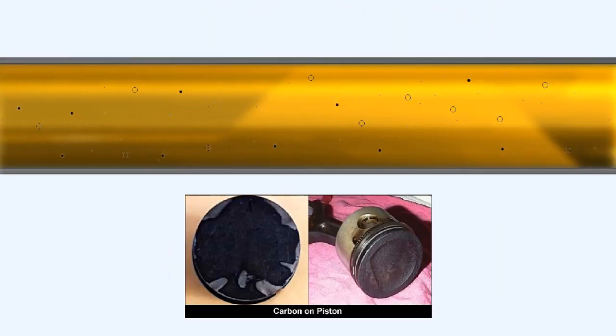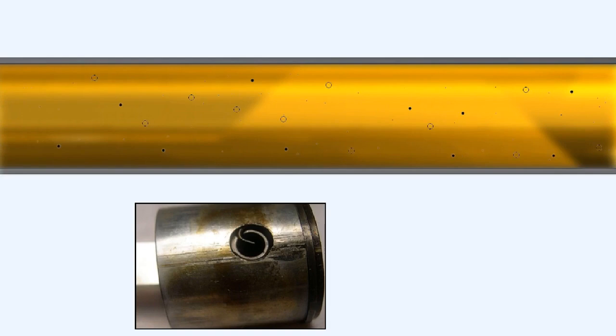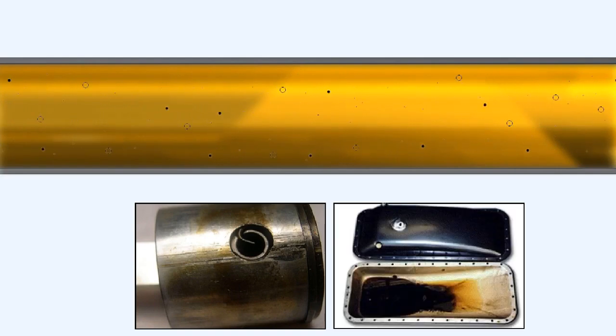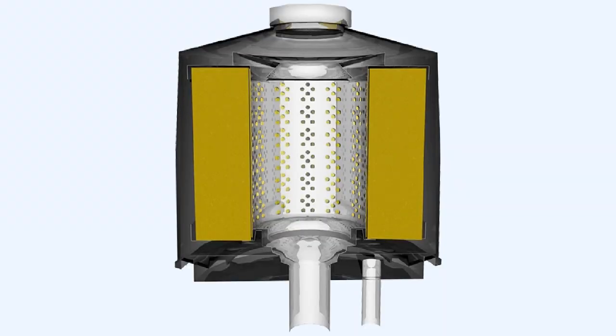As the oil flows through the engine, it also carries away unwanted foreign particles, and also the byproducts of the combustion process, such as carbon, which forms on the piston crown, varnish, which forms on the piston skirts, and grease-like sludge in the crankcase. These deposits are strained out of the oil by the oil filter. Thus the oil can be said to clean the engine.